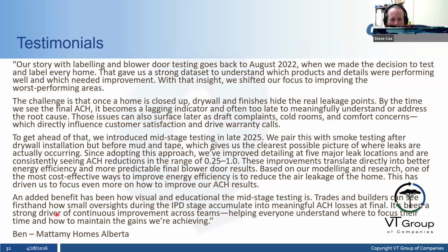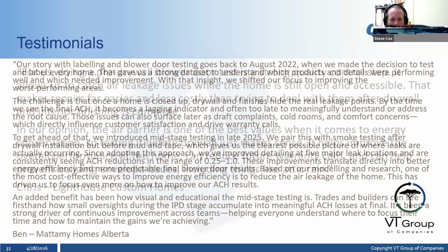And then Ben also says an added benefit has been how visual and educational mid-stage testing is. Trades can see firsthand how some small oversights during the IPD stage can accumulate into meaningful ACH losses at final. It's been a strong driver of continuous improvement across the teams, helping everyone understand where to focus their time and how to maintain the gains that we're achieving. So that's how someone like Mattamy Homes sees this.